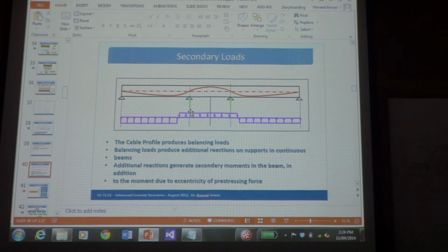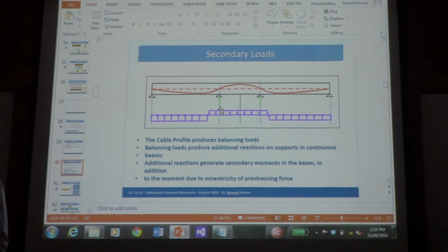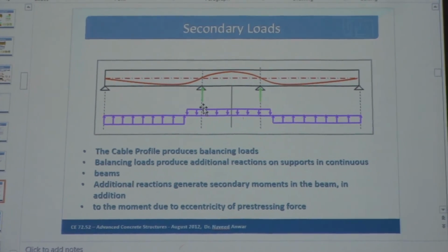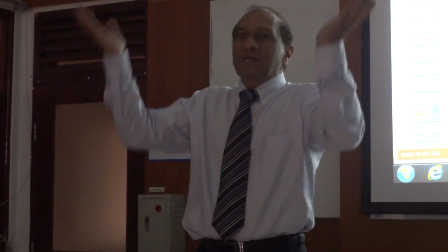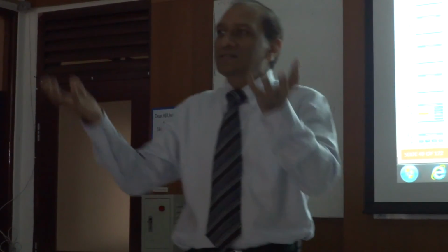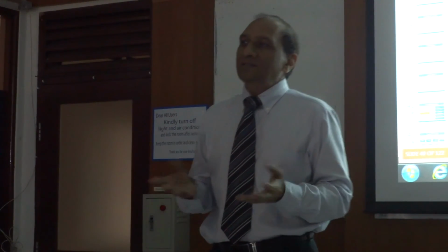So we are saying that vertical forces are generated in the structure because of horizontal forces, right, in a beam, which normally should not happen. But here it is happening because the tendon is curved and it is trying to straighten out. So it pushes some supports down, it pulls some supports up. Internally, a completely internal self-contained loading is generated, which is balanced but causing bending moment on the structure.